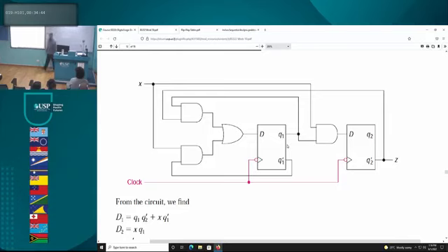D1, all right. Let's trace it once more. We're doing a repeat trace from yesterday. That's an AND gate, right? What's coming into this AND gate? Q1. Can you see that Q1 is coming in there? What about this guy here? Q2. So it's Q1 and Q2. That's a mistake which we made yesterday.